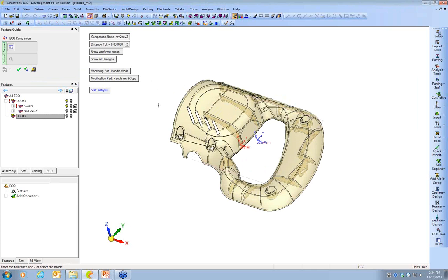Okay, well the idea from here on out then is that we're going to apply whatever new changes we get directly into the design at the current point of working. When we go that route, the comparisons are always made directly against our work file. After all, the work file is what distributes the part data down into the mold design. It's the model that is the customer part in the as molded state. Okay. So we'll run this analysis.